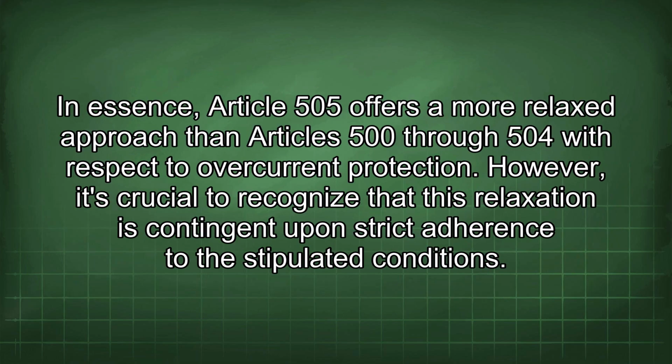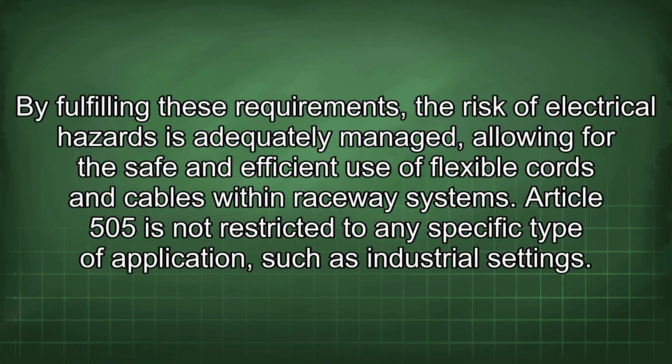In essence, Article 505 offers a more relaxed approach than Articles 500 through 504 with respect to overcurrent protection. However, it's crucial to recognize that this relaxation is contingent upon strict adherence to the stipulated conditions. By fulfilling these requirements, the risk of electrical hazards is adequately managed, allowing for the safe and efficient use of flexible cords and cables within raceway systems.